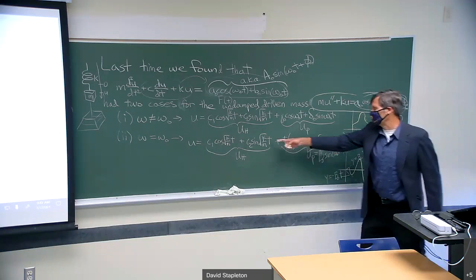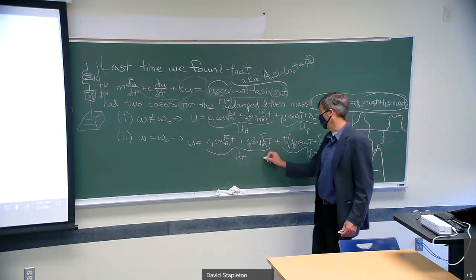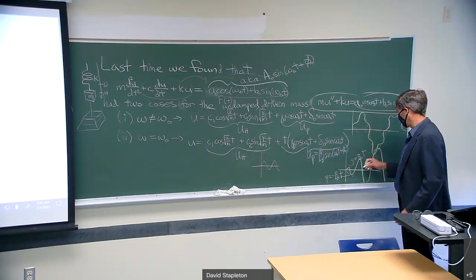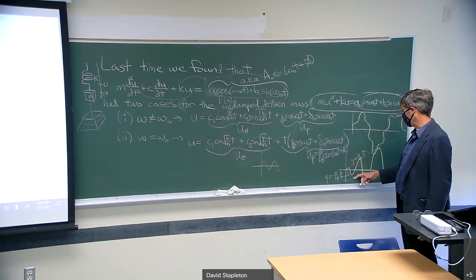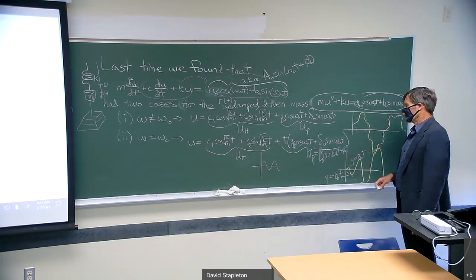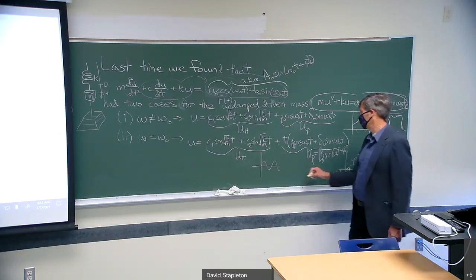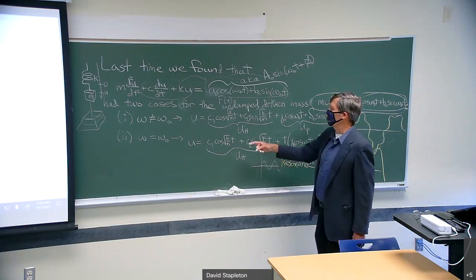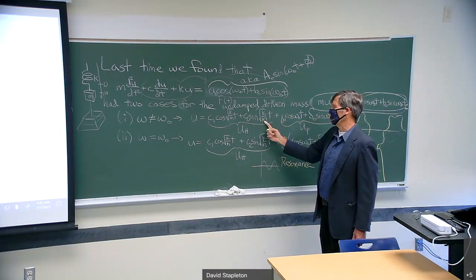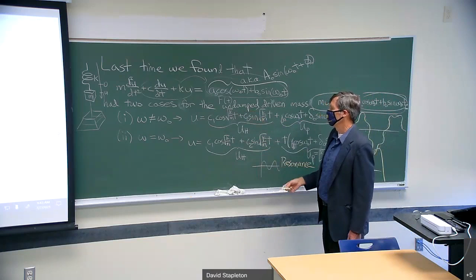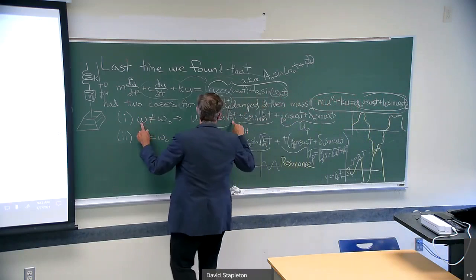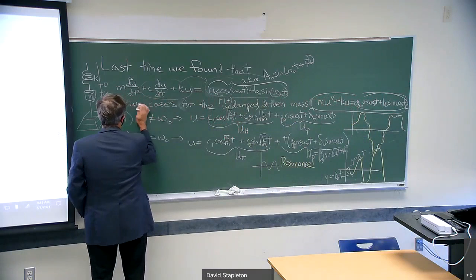And then when you add it to this one, which is just a sine wave, what you get is something that eventually looks mostly like that one, right? It's just that one oscillating around this one. All right, so that's called resonance. If you push it at the same frequency that the system wants to naturally oscillate at, square root of k over m. And maybe I better make it clear, I said omega, I mean omega is the square root of k over m, the original system. So omega or square root of k over m would be more enlightening, wouldn't it?